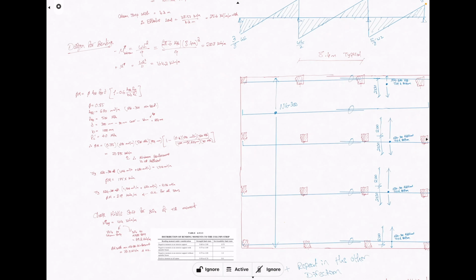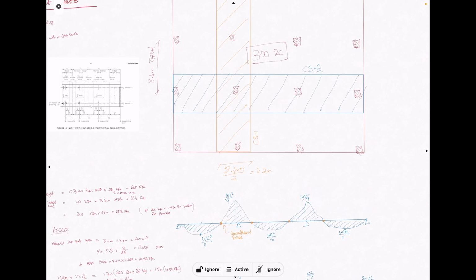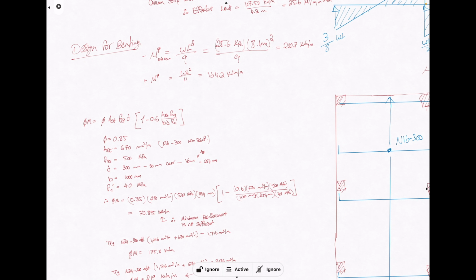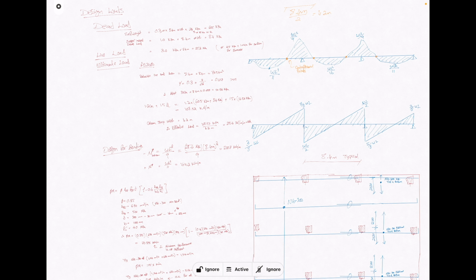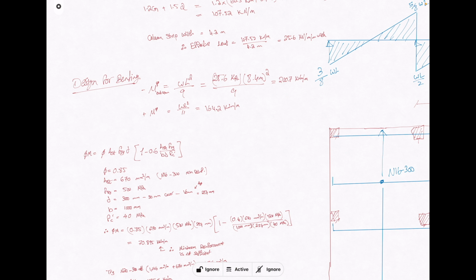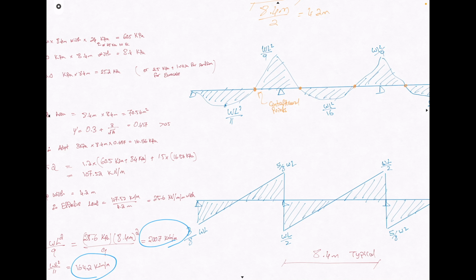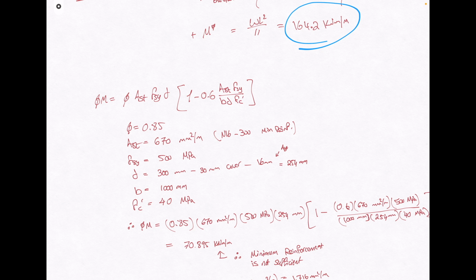Now looking at our design example 2, which if you remember was our flat plate design. Again, for bending, we can put the numbers into our calculated bending moment diagrams, and from there we can get our hogging design moment at the end span, and we can get our design sagging moment at the end span, because as we can see, the critical is always the end span and not really the internal ones. So once we have that calculated, now it's time to plug into our equation again.